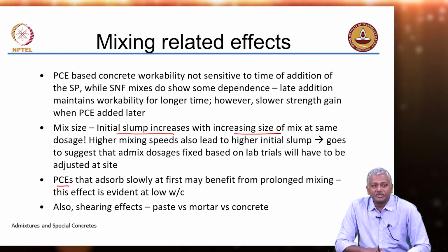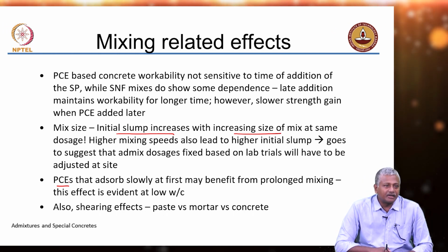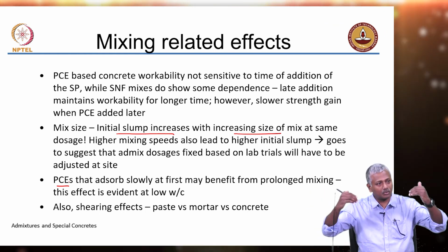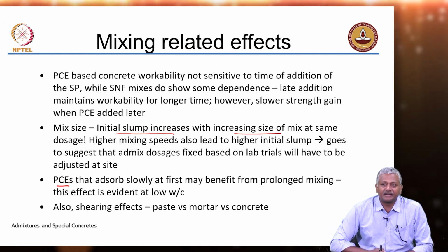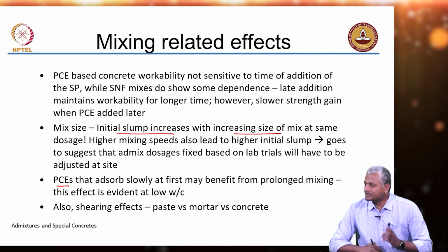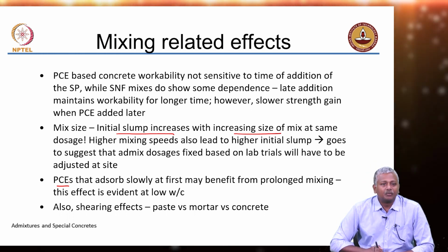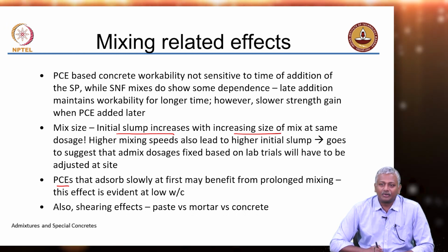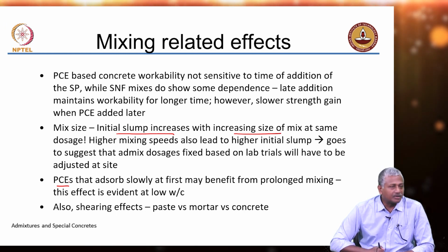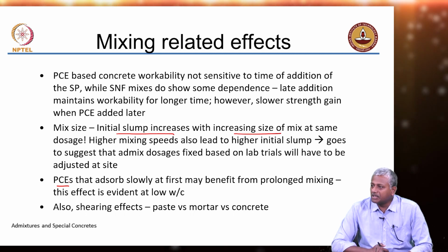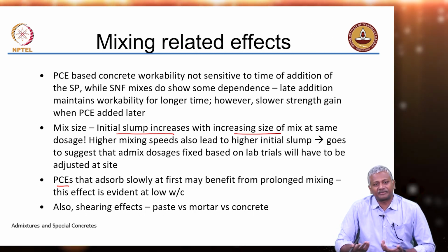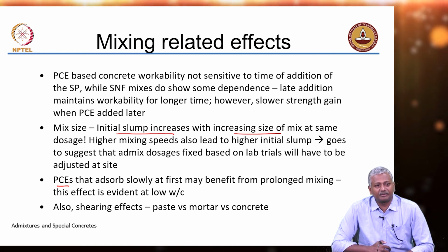And they do this 1 minute mixing. Of course, batching will take a little bit longer, because all the aggregate, cement, admixture, water, everything has to come into the mixing drum. But after it comes, mixing is hardly done for 1 minute. Okay. Now, this 1 minute mixing is actually not optimal at all for concrete. When we do this 5 minute or 10 minute mixing, it's in the lab typically, right? You have to mix. How long should you mix actually? What's the objective of mixing longer?